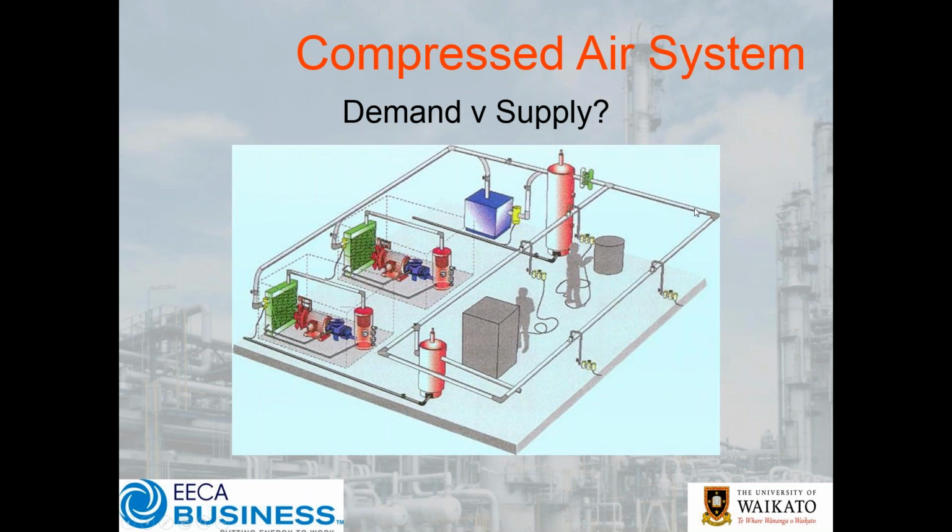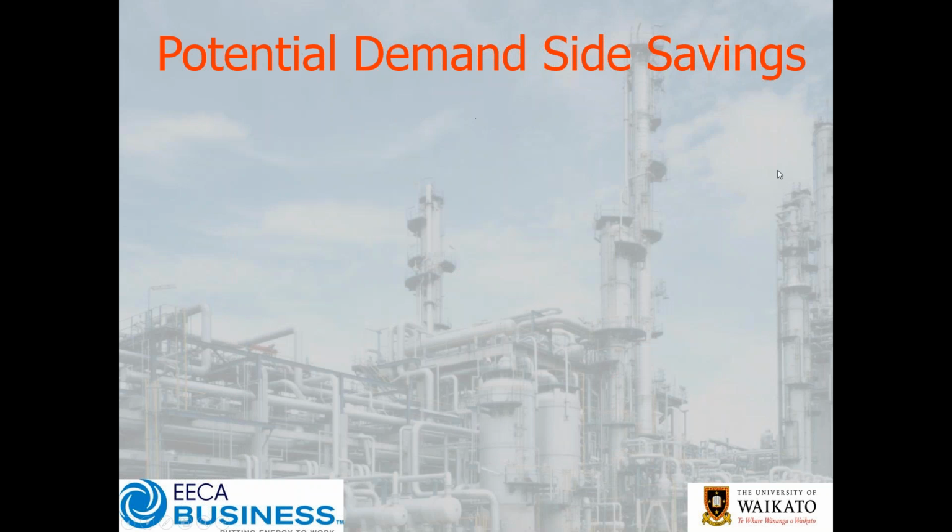and what the pros and cons are. So just to reiterate, we have the supply side where the compressed air is generated and treated, and in some cases stored, and then obviously the demand side where it's used. And oftentimes as your sites get bigger, you have a substantial distribution component joining the two together. The beauty, of course, is that once the air is sent down the line, generally you don't need to worry about it coming back like you would with steam and condensate systems.